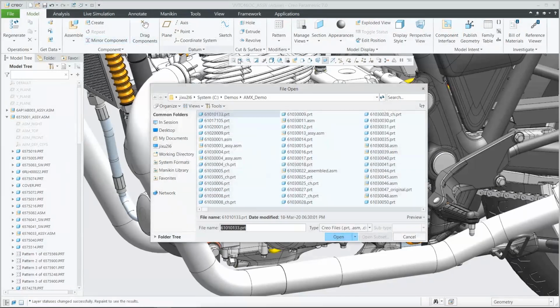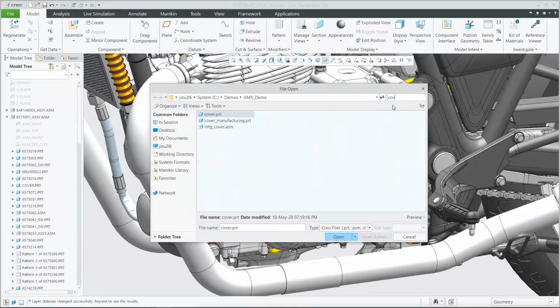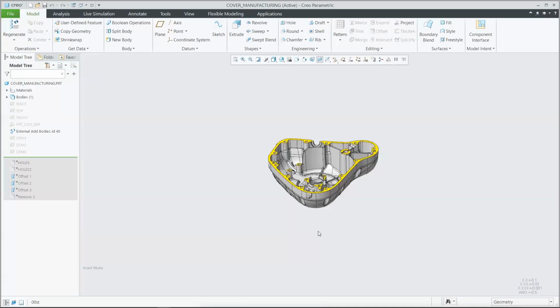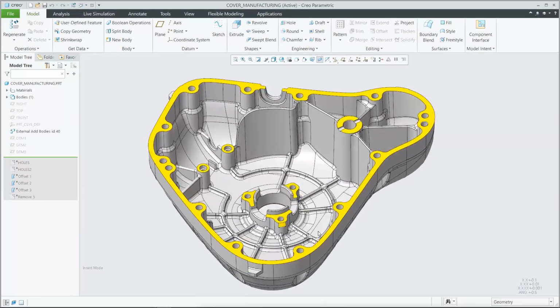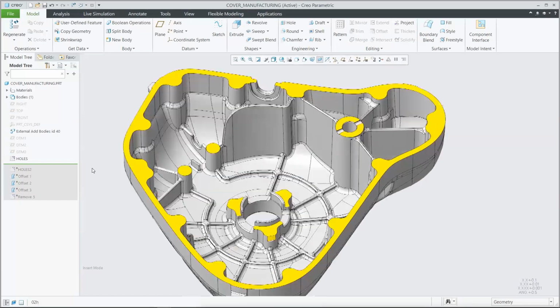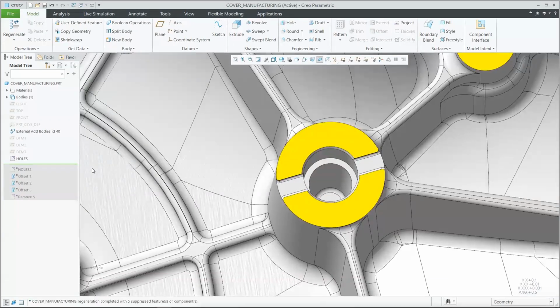So what I'm going to do instead, first and foremost, is use additive manufacturing to create the main shape for this. What this is going to do for us is allow us to work with some materials that might not do very well with something like a casting, but whenever it comes to 3D printing, we have no problems whatsoever. So what you're looking at here is essentially what it would be before you would go through and maybe machine off some of these finer edges.